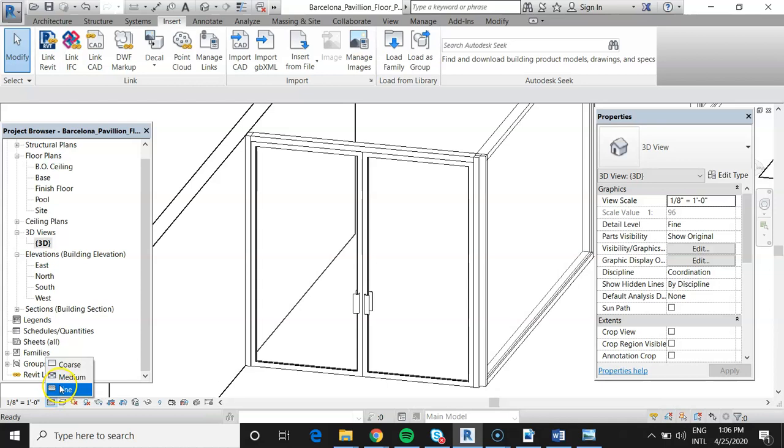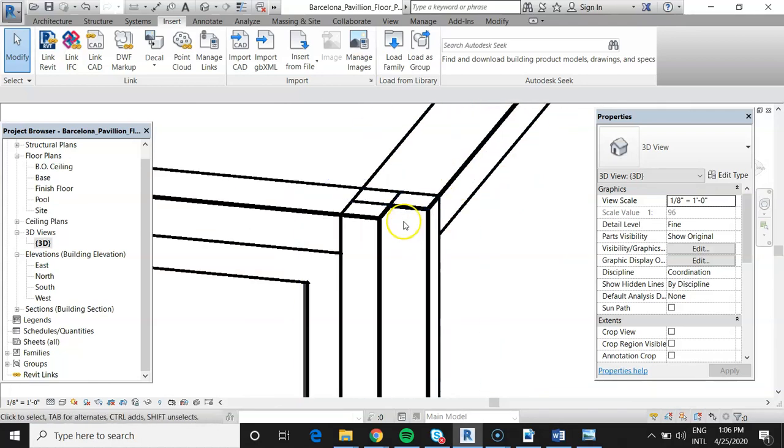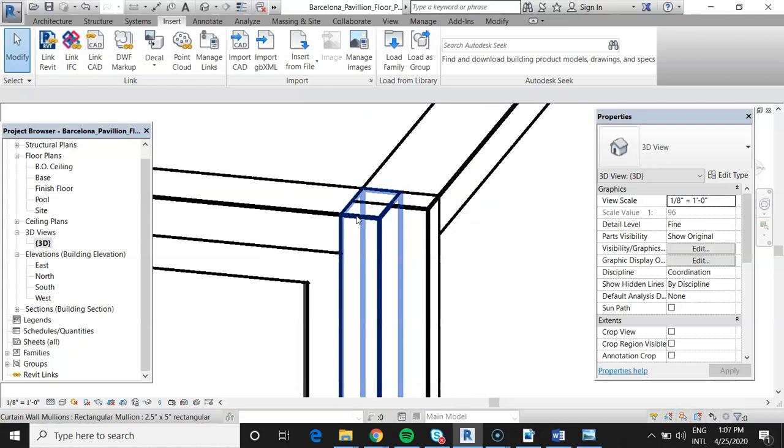But again, like in my first introduction to the whole program, we talked about this, and I gave the example of the structural timbers. If you ever work with those, if you're on coarse or medium, they just show up as single lines, but you have to come into fine for them to actually show up as three-dimensional objects. So a little peculiar. Sometimes you have to be aware that that's the case. The other thing I want to take care of is this corner, which is not so attractive. As we have a, get to my tabbing. So there.